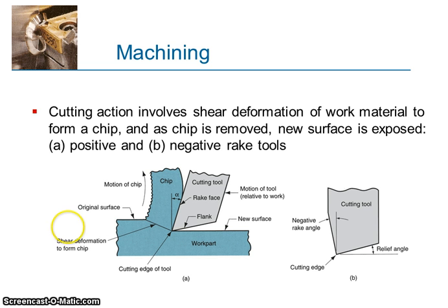As you can see in the picture, the cutting tool penetrates into the workpiece. The cutting tool is subjected to compressive forces. So as soon as the workpiece crosses its elastic limit and proceeds into the plastic limit, the chip shears itself from the region. This shearing occurs in the shear plane.